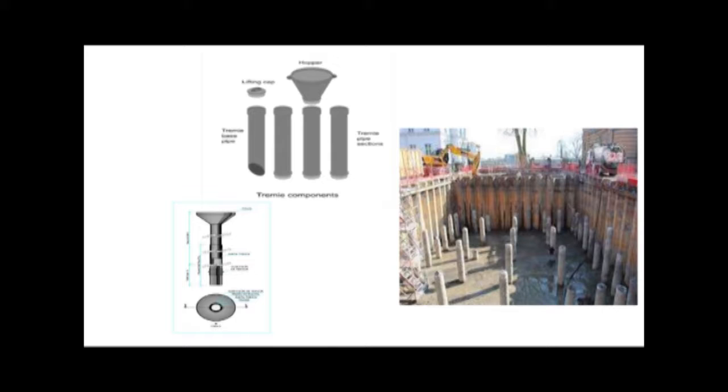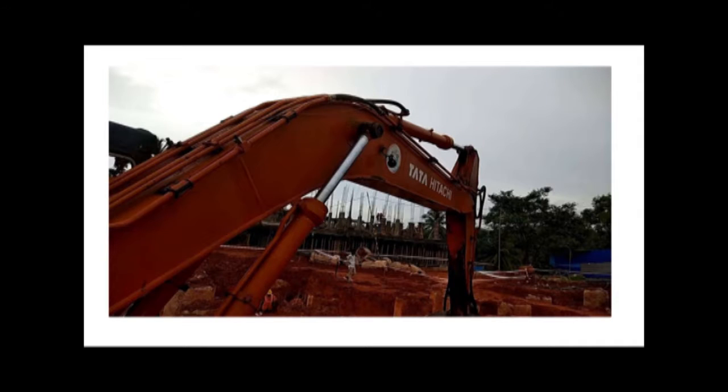So what is recommended by codes is that you go for a 10% higher mix. You already design the mix at the higher end, because you are aware that on site when you do the concreting, it will lose its concentration, because there is water already present in it. The mix will dilute. So for that reason we have to go for the higher mixes at the design end, so that the desirable mix can be achieved at the construction site.